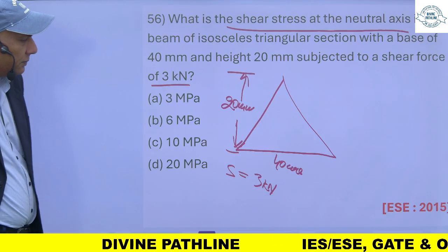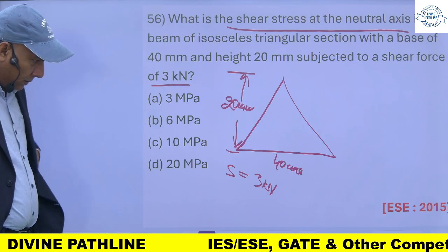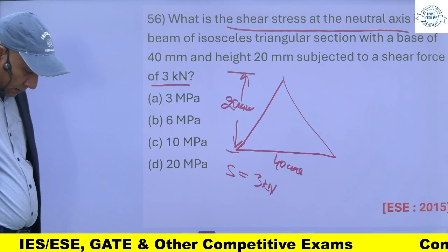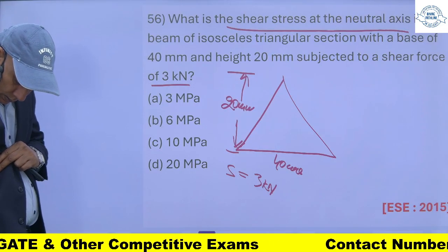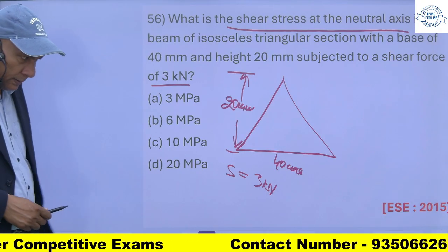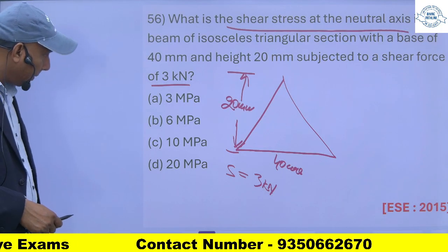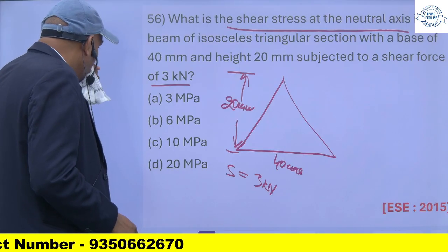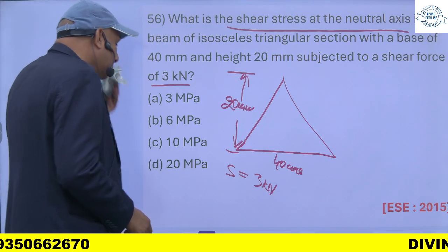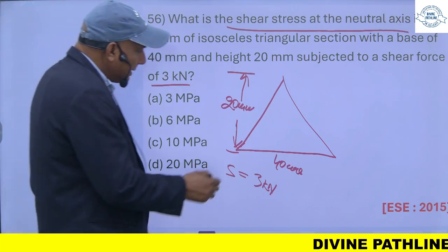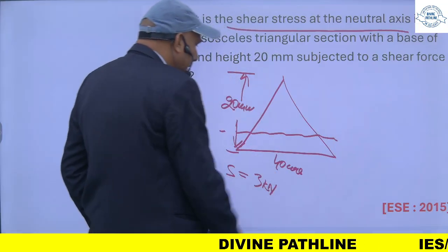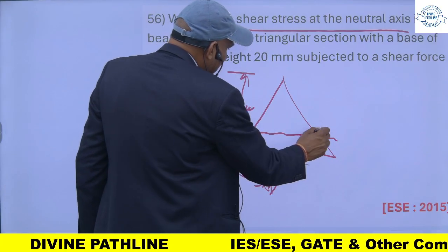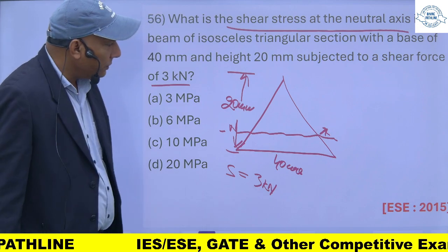So for this, first we must know, in case of triangular sections, my shear stress, suppose this is neutral axis, will not be maximum at the neutral axis.